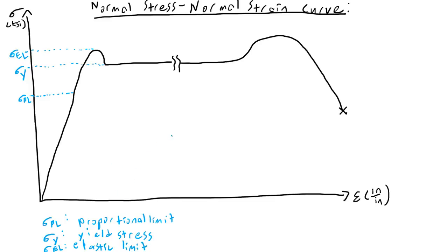Let's see, what other sigmas do we have? Well, we'll need the sigma ultimate. The stress here is the sigma ultimate. Sigma ultimate is, as it's described, the ultimate stress that the material can ever withstand. And it's only after a long range of yielding that this happens. So this is the most you will ever get out of the sample of material. This is past the point of yielding. It is now completely finished. This is the maximum load you will ever get this thing to carry. And even then, to that point, it's permanently deformed.